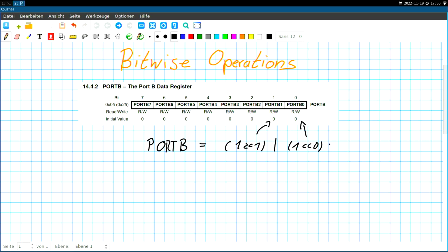And what the compiler will do is see this macro and substitute it with the address of this register in the address space of the microcontroller. The cool thing about using these macros is that if we want to port our application to another microcontroller with a different memory mapping, the compiler would automatically change this macro into the right address. So this is very convenient.